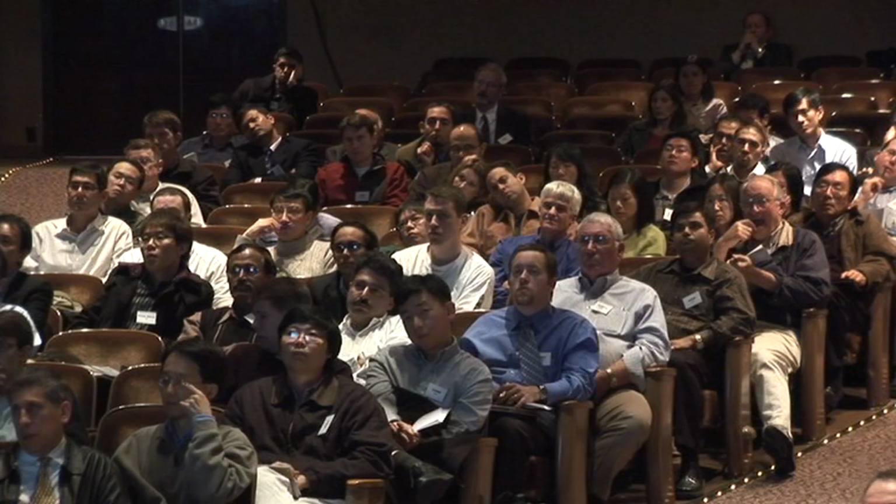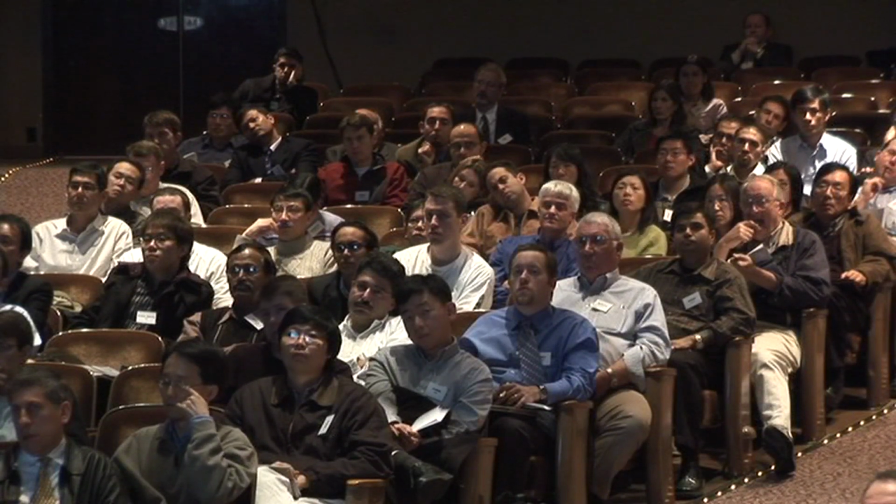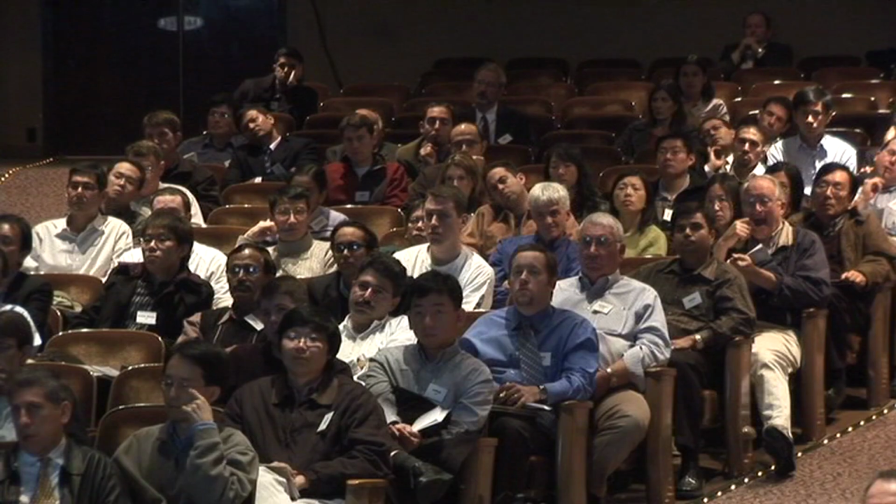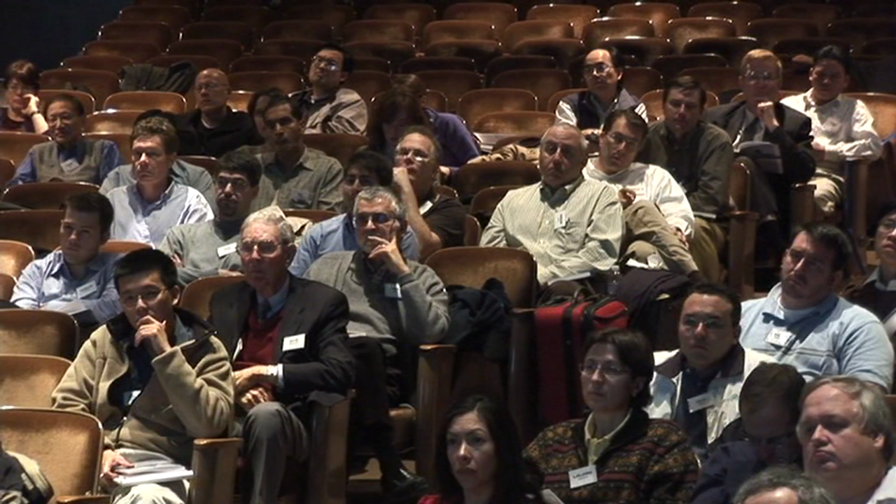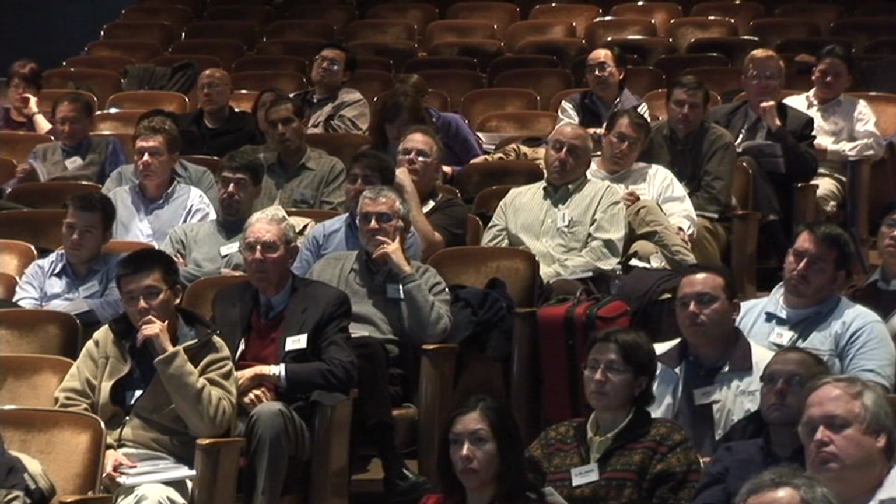So I've sort of accounted for some of the axial force effects, but have I really accounted for them? I'm not really sure whether this is right. And it makes a substantial difference, by the way. And one of the things here is these things can happen when you do nonlinear analysis. So you have to be careful. It's not a matter of plugging into a computer program and doing analysis and believing the results, because you're just analyzing your model. You have to be a good engineer, and you have to understand what's going on behind those results.